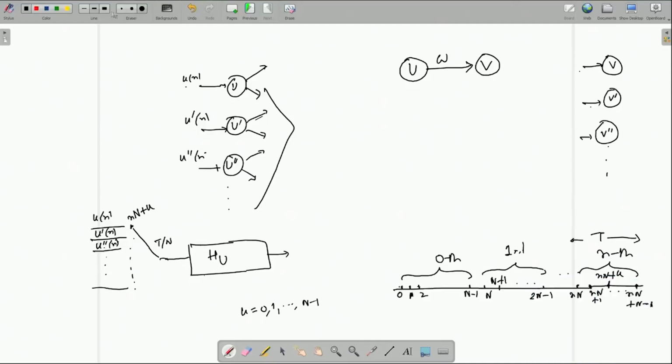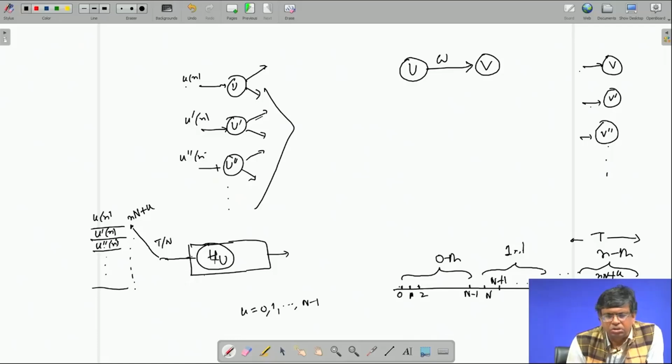This is the hardware unit, say an adder or a multiplier. Why is it necessary? Because the system is working at a faster rate, so the original critical path of the hardware unit may not be short enough to process data at that rate. So it may be necessary to do some pipelining by forward path cuts and retiming.